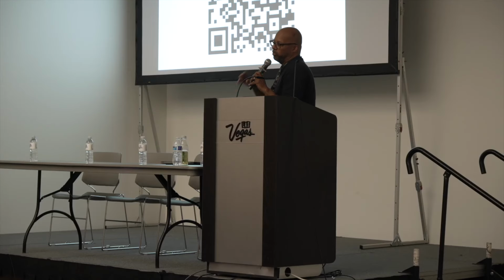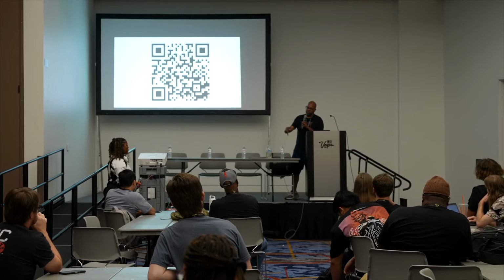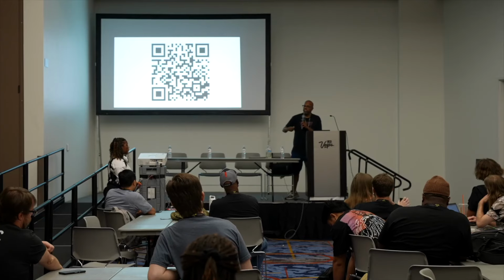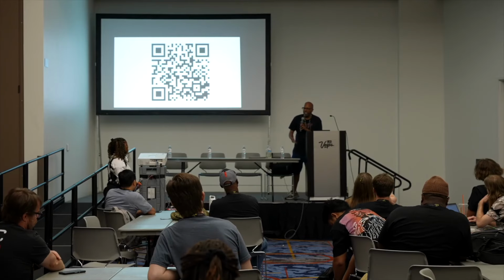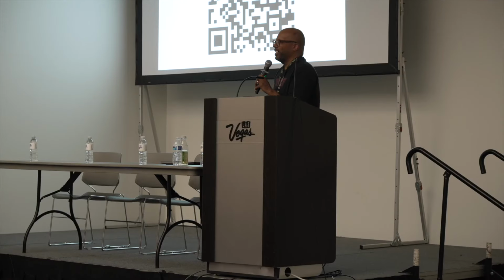Generally, debugging, like setting breakpoints, is harder on an embedded system, because when you set a breakpoint you change the memory value. A lot of these embedded systems run in firmware, so you have to change the firmware to set the breakpoint, but you can't reflash every time you want to set one. So a lot of times people will use a JTAG debugger. I just didn't cover it as a whole, and you can get tons of information out with those.